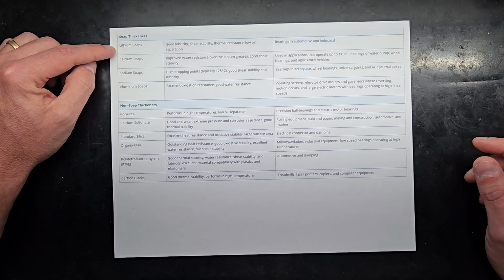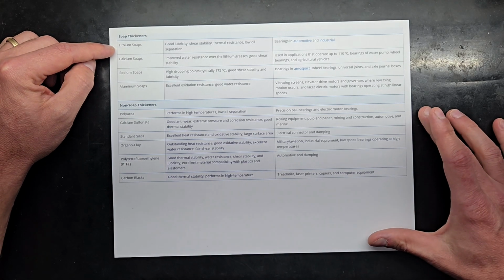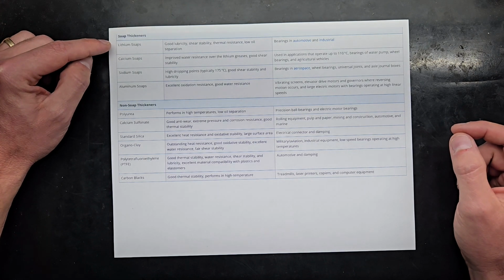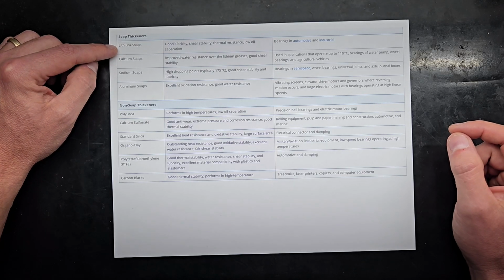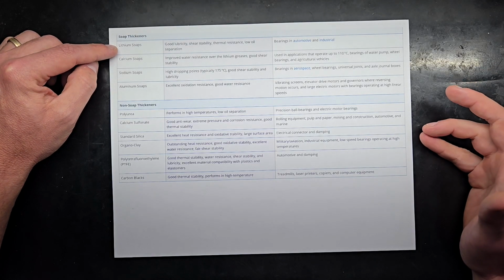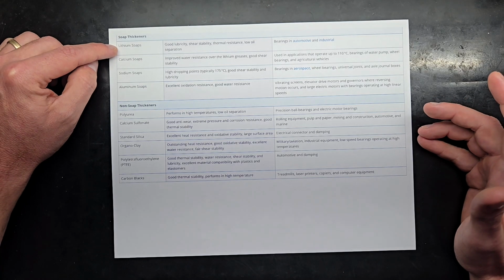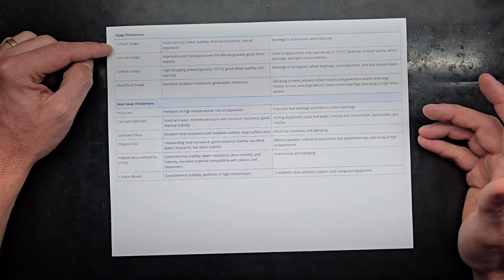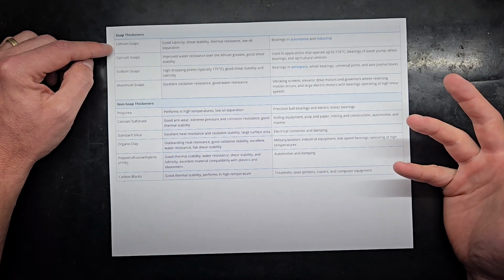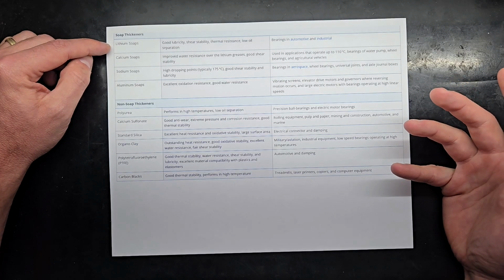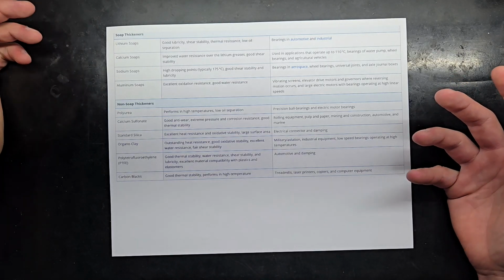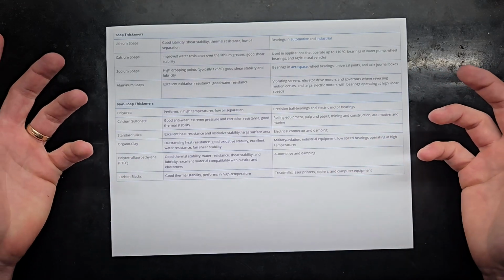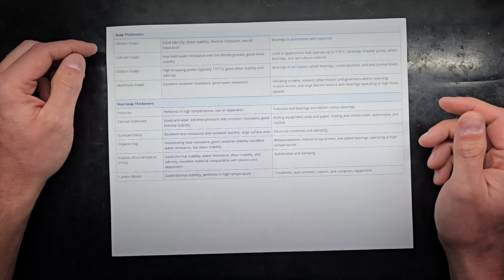The reason a naphthenic base oil is the more prominent or most likely if you're buying a fully synthetic lithium soap is because the way the structure of that base oil increases the yield of the thickener. So they're able to make more of the lithium thickener when they use a naphthenic base oil because there's reaction kinetics and it's advantageous and you get more product for cheaper essentially.